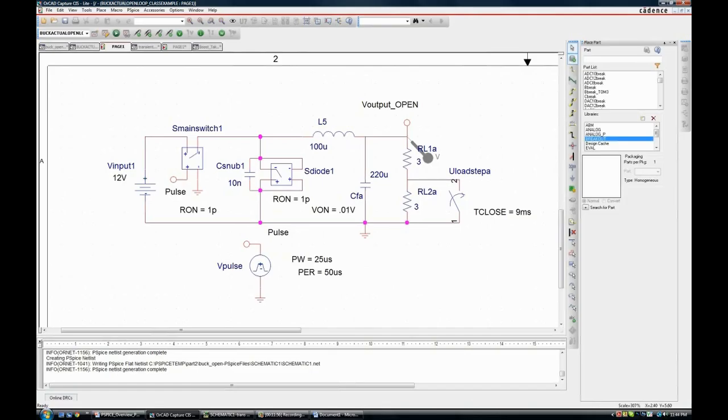So a way to solve that problem, particularly when you see during a convergence failure that the voltages at a node were extremely small or very large, actually just extremes in general, is to put a capacitor across those two points, across those nodes, to try to slow that change somewhat. So that's what these numbers are for. It's a means to manage convergence. So let me zoom back out.